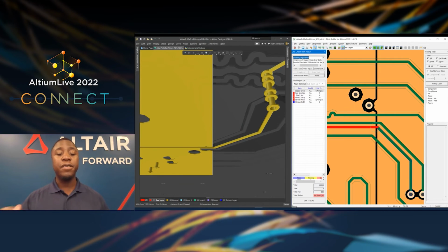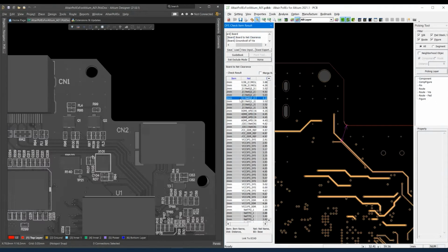We now can go to some of our other checks that we have. In this case, some of our nets and how close they are to the board edge. This is important because, as you can see, there are certain components that may influence the design. And when you're having design reviews, you're able to understand more than just looking at it from a single view of the layers, but also maybe you have the part models right next to it in your Altium Designer, and we can understand, is this a critical part? Can we move the footprint such that we can have more spacing for the nets, if they're both on the same layer?